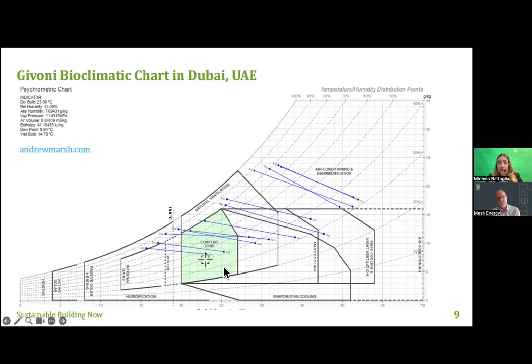Using passive design strategies, we are able to avoid air conditioning for much of the year, but for sure, if we're using a glazed facade in a country like Dubai, where it's always hot, then the glazed facade reacts like a radiator. And do we really need a radiator in a climate like Dubai? I don't think so. But here, people love the view because it's luxury, it's cool for sure, but this is not sustainable in a country like Dubai.